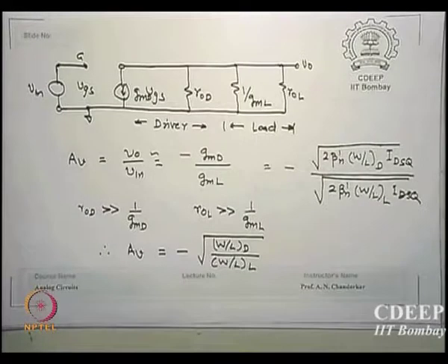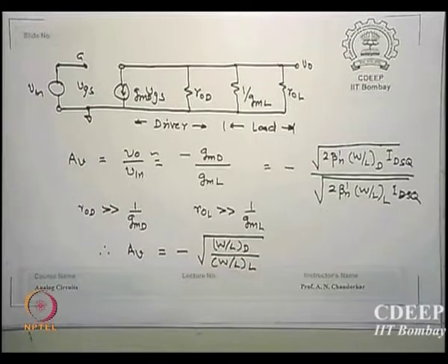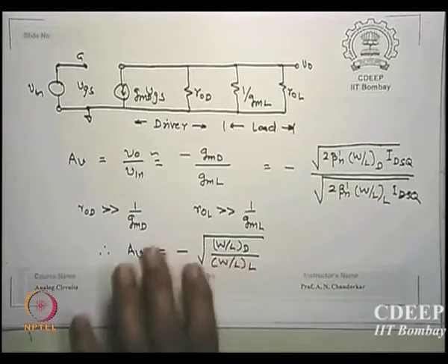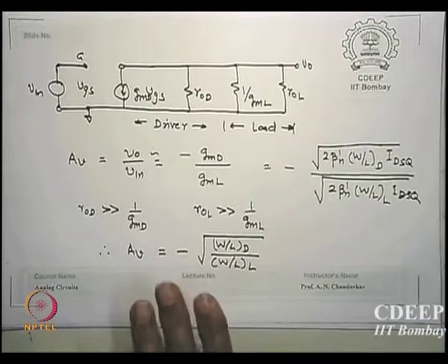That is how we do gain adjustment in silicon chips. An NMOS amplifier on a silicon, I will design an amplifier of this kind and change the sizes, okay, to get my gains. Is that correct? Do you also see interestingly here there is no device parameter, basic technology device parameter except W by L, which is size, which is controlling it. Sizes of course can vary.